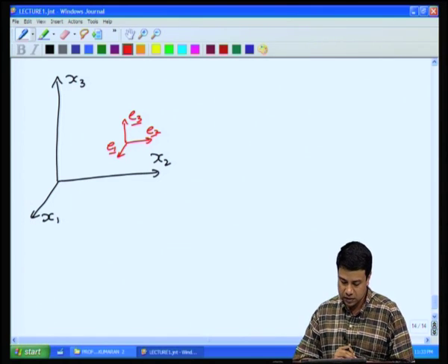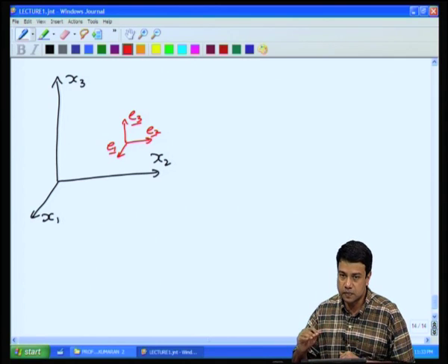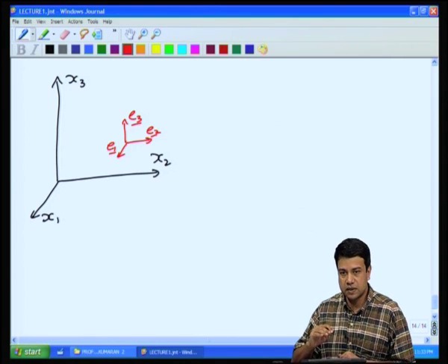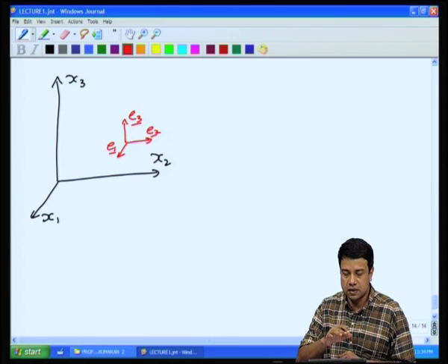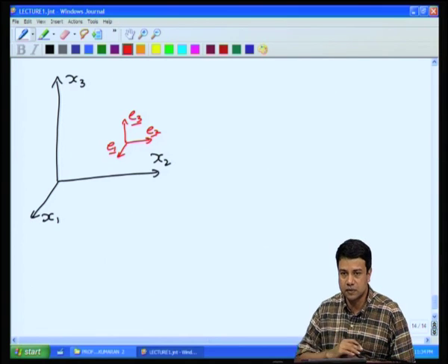And if I can derive a conservation equation in this coordinate system for a vector, without reference to its individual components, the conservation equation is a property of that vector itself. So, it is independent of coordinate system. It is going to be the same whether I use spherical or cylindrical coordinate systems, so long as my vector quantities and vector derivatives are correctly framed in that other coordinate system.